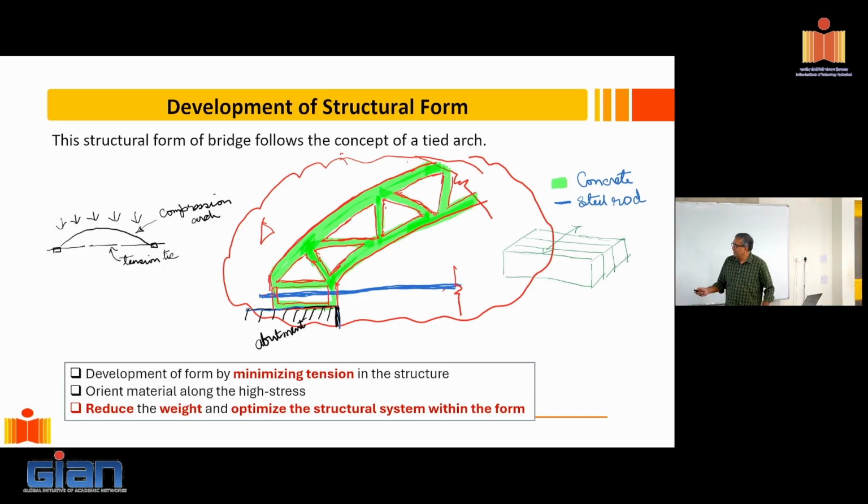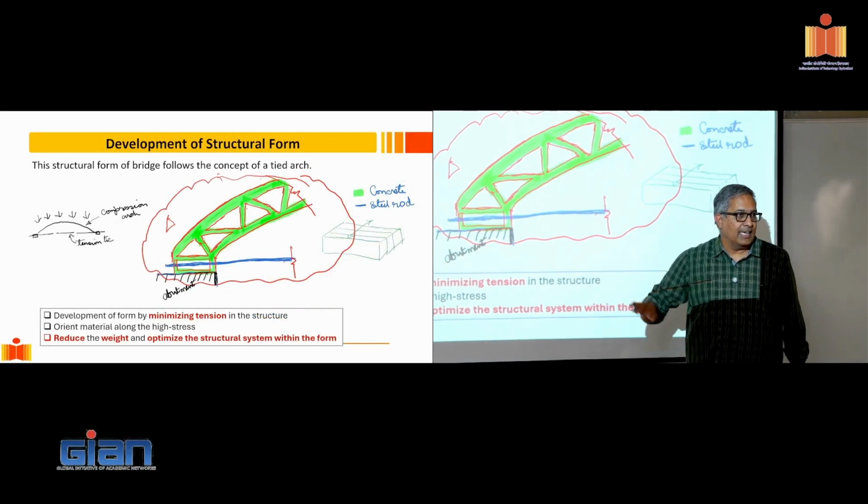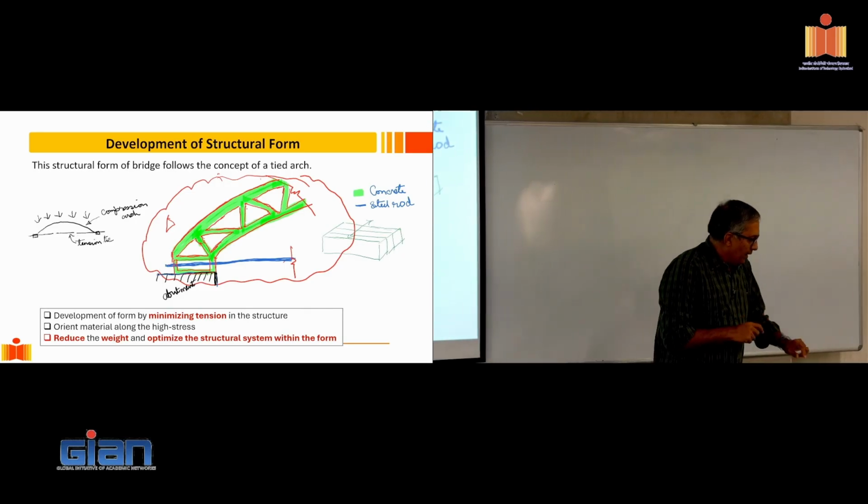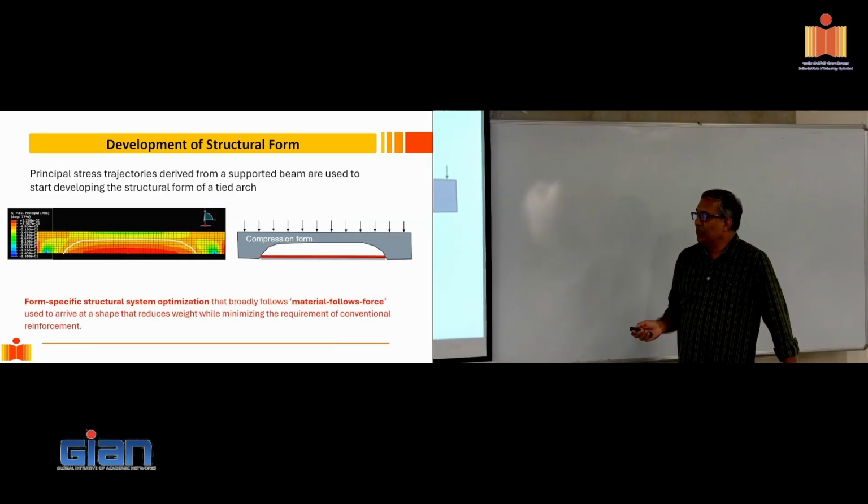Now, these are literally from my notes. So basically the idea was that I'd print here, so this would be my direction U, right? My V direction would be in this direction here, and the W would be basically going into the plane of the board. So that was the idea of this printing. Right? So what am I achieving with this? I'm aligning the strongest direction of the material with the structural element, right? And the weakest is going to be perpendicular to the board. So basically the weakest layers would be stacked up behind, going inside and outside the plane of this board, right? So now the idea was to come up with this compression form.